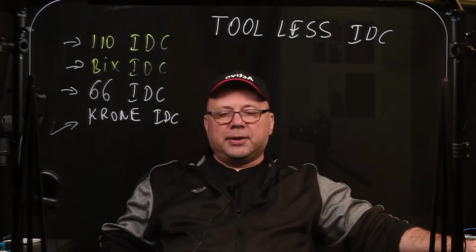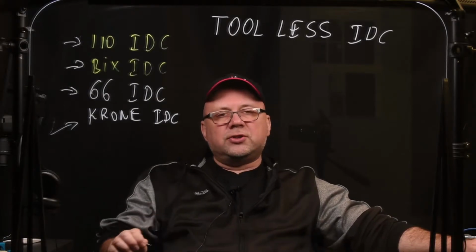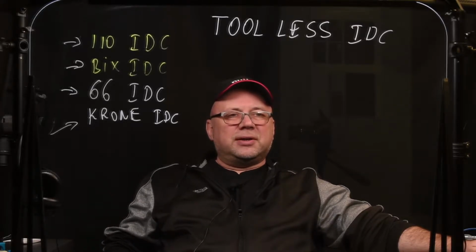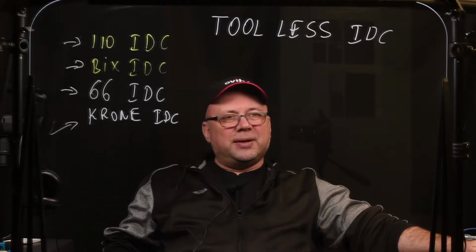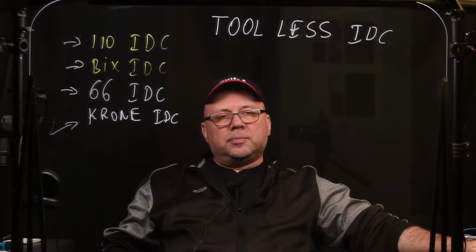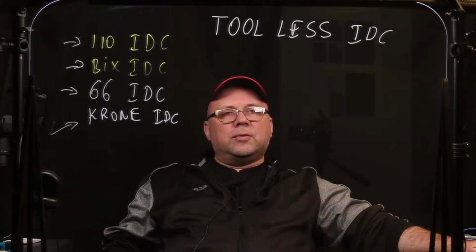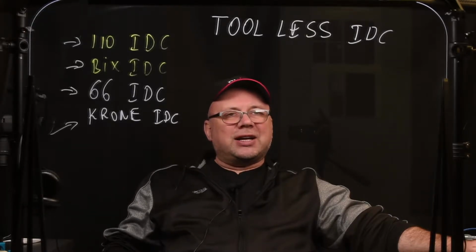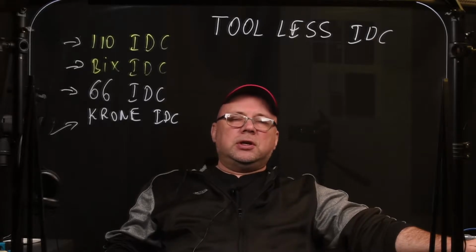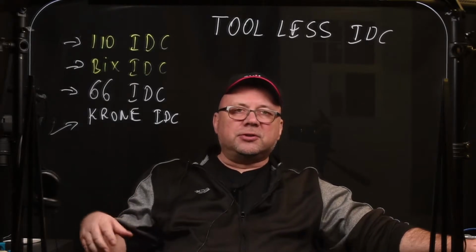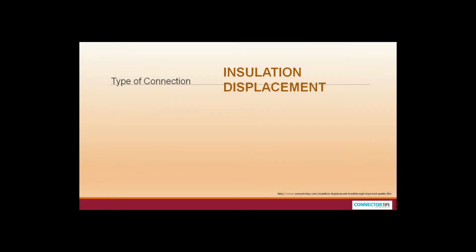In the past, a lot of soldered connections were used. Soldered connections are good, except they take too much time; it takes longer to perform a soldered connection. When it comes to installing cables and cable structure systems commercially, speed and efficiency come into play. So the insulation displacement connection was invented. Now it looks like this.